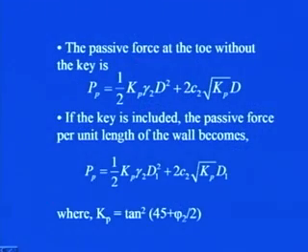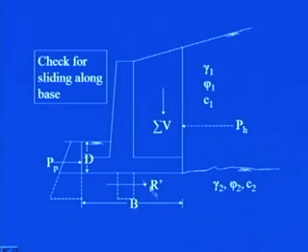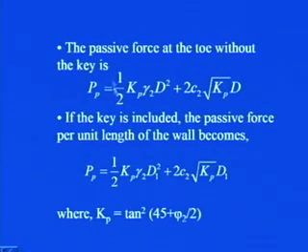Some of the key points related to this aspect are very important and you must keep them in mind, so let us put them in words. The passive force at the toe without the key, where the passive force is generated over the depth d only, has the expression half Kp gamma 2 d square plus 2 c2 square root of Kp into d. Now, if the key is included, the passive force will become...